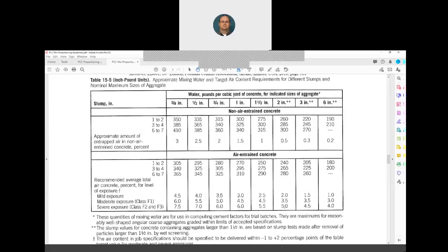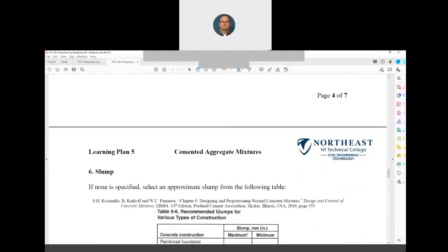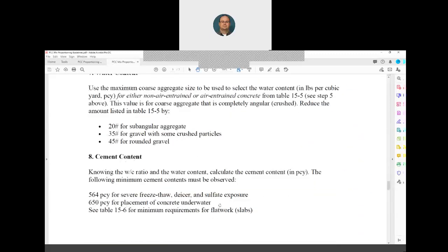Remember, that's tiny air bubbles. That's physical volume space. So if I take 27 cubic feet times 0.06, that is how many cubic feet of airspace that 6% air will equal in that cubic yard of concrete. The example hopefully will clarify that.